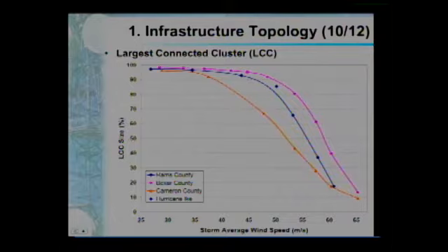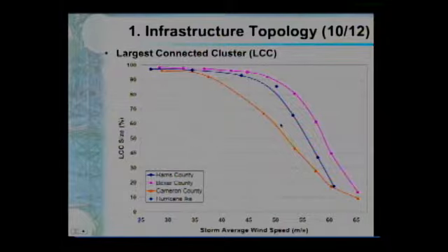So when the wind speed is relatively low, I have it here in meters per second, and for your reference, this dot here is Hurricane Ike, whose maximum wind speeds on average were 110 miles per hour. So that will help you making the transformation. So for low wind speeds, what fails the most are the transmission lines, the links. And some networks can withstand that without seeing major losses on performance. When the wind speed really gets high, then we see declines for all of them, and that's because the electrical substations now start failing.